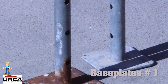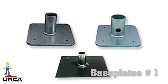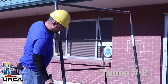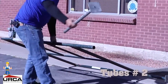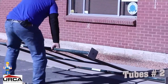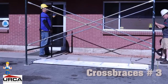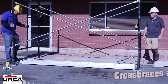Component number 1, base plate. Load-bearing base for the scaffold. There are many types of scaffold support base plates. Component number 2, tubes. Tubes with connectors serve as the upright component of a scaffold and transfer the entire mass of the structure to the base plate and are made either of galvanized steel or aluminum. Component number 3, cross braces. Cross bracing ensures structural integrity, but not all tube and coupler scaffolds have them.